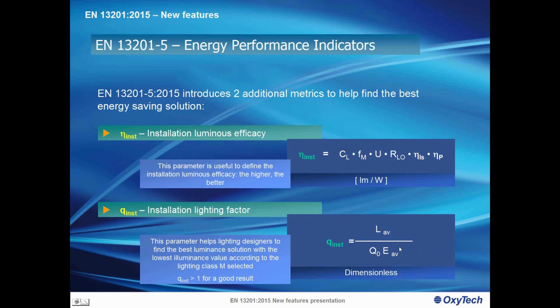It means that if we keep, for example, the illuminance at the same level, we can improve luminance if we also improve the Q0. So, for example, if we have an asphalt, in place of being completely black, we use a gray asphalt, which has a higher Q0, for sure we're going to have a better L average, so the average luminance.